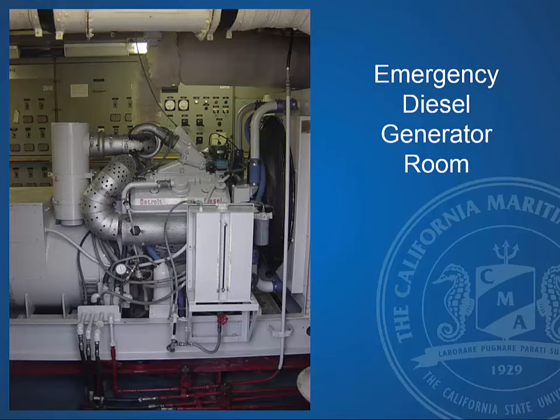In this case too, you have the emergency generator day tank to supply you with a minimum of 24 hours of fuel, and you have a hydraulic start system on this vessel, which is a very, very good method. It gives you the highest cranking speeds.